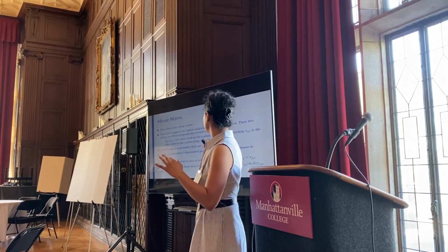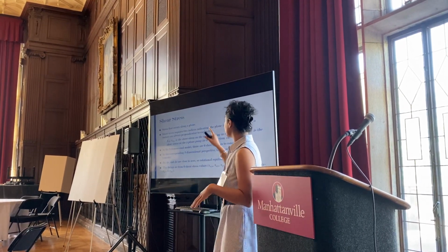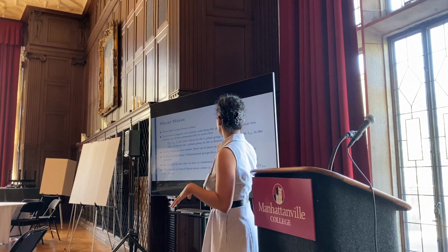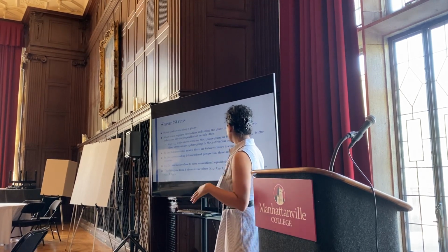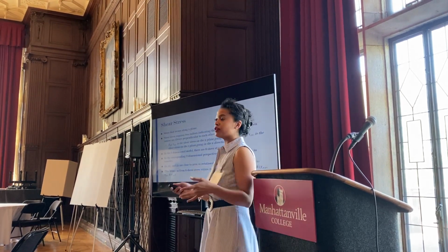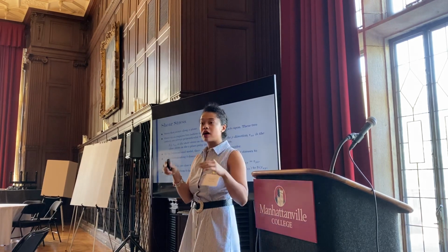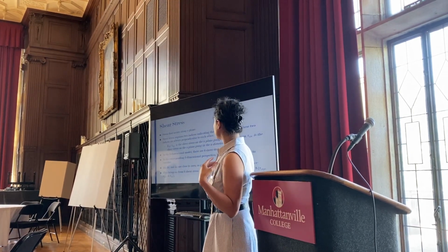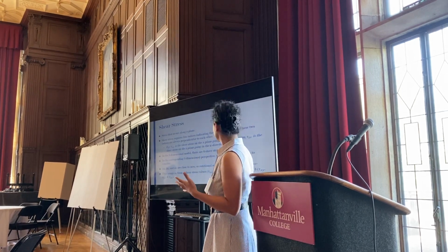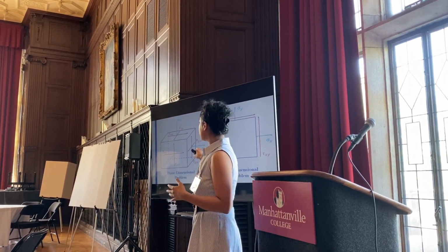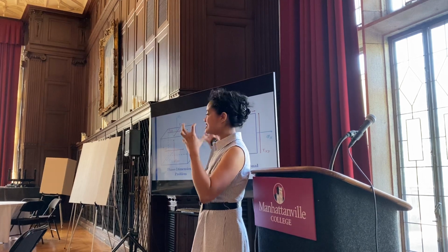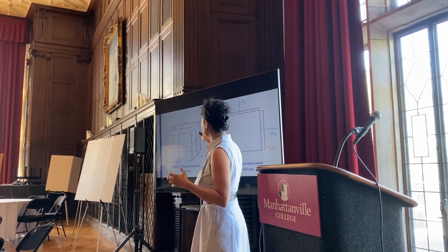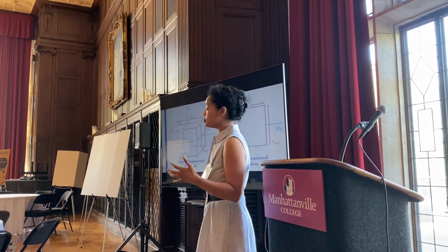So we can use rotational equilibrium to see that our shear stresses, as long as they share the same index values, are equivalent to each other. For example, tau sub xy is equivalent to tau sub yx. That brings us from 6 shear stress values down to 3. Here is an example to help you see the shear stresses in comparison to the normal stresses.